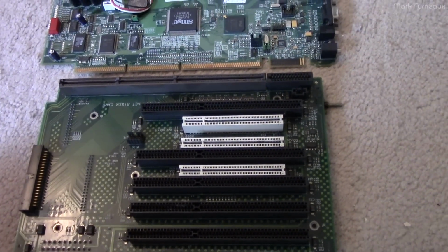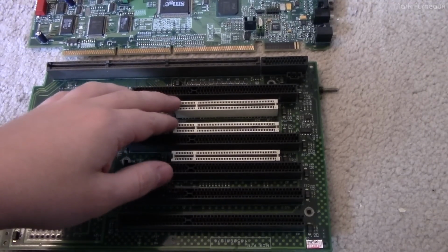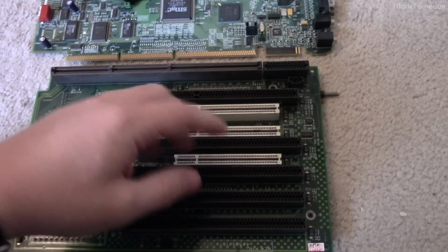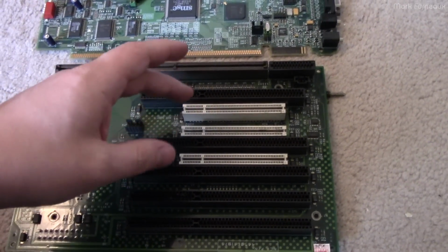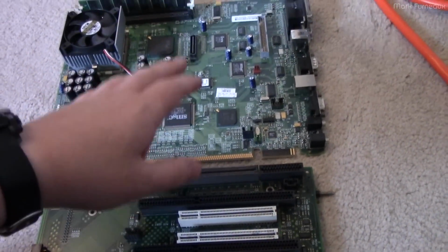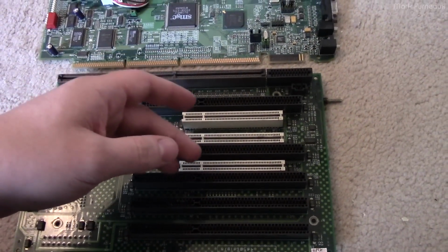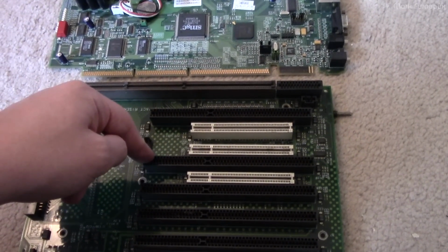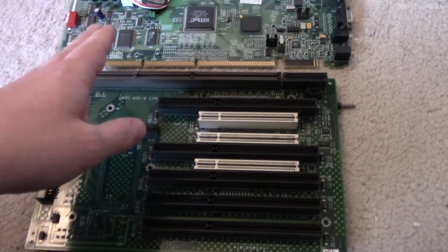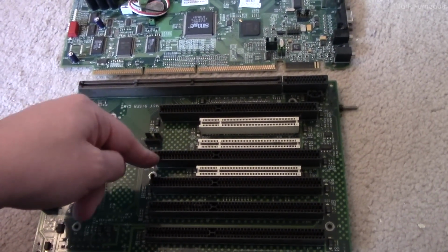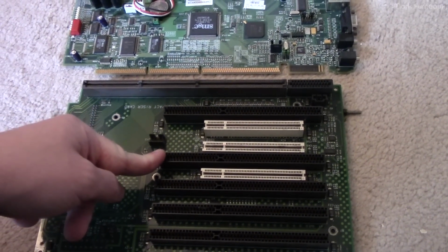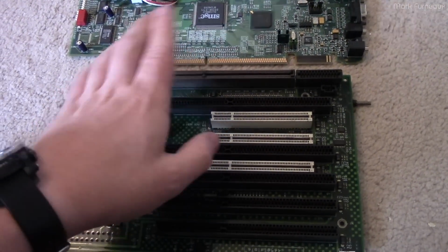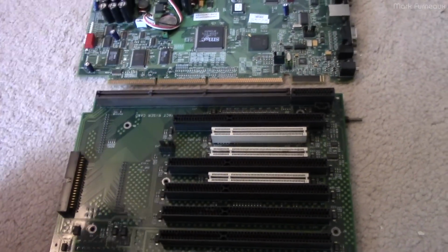Now, you may have seen, probably around the time when PCI went out of style, motherboards that actually had both PCI Express and PCI slots, even though the platform, like the CPU and the chipset, didn't have any PCI capabilities, because PCI is not part of the IBM PC spec. ISA is. So even your brand new AMD 7000 series or Intel Rocket Lake CPU has an ISA bus. Even though it's likely not connected to anything, it exists. It must exist. In order for a computer to be a PC, it must have an ISA bus. But PCI is not in the spec, so they dropped that in favor of PCI Express as fast as they could.